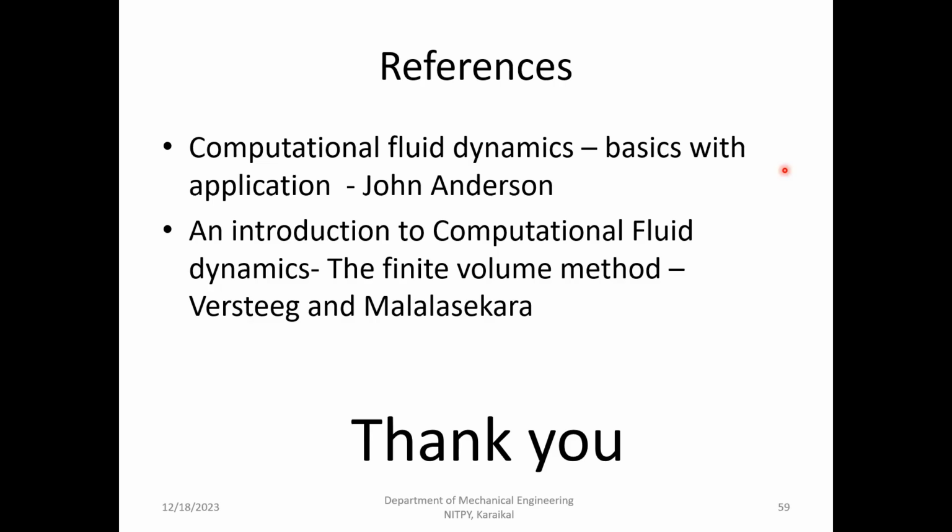Regarding the selection process, which one is best for a heat exchanger? Heat exchangers, you're saying, whether it's cross flow or counter flow heat exchanger. You are not going to go with high speed flows or supersonic flows. So you can go with SIMPLE or SIMPLER, which will do it. When you go with supersonic flows, then we can look at different kinds of things. But for a normal heat exchanger, SIMPLE or SIMPLER will be able to solve it.